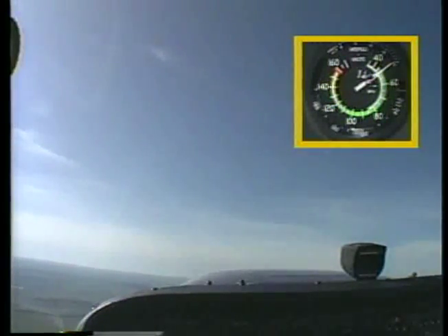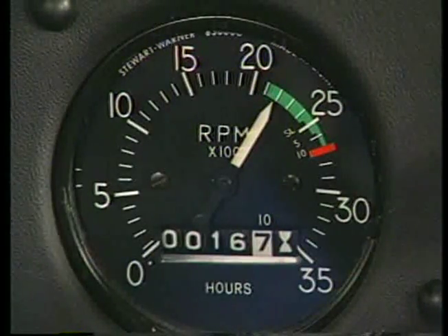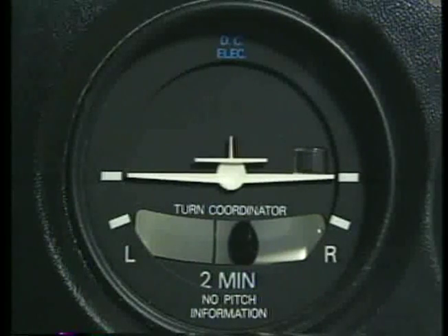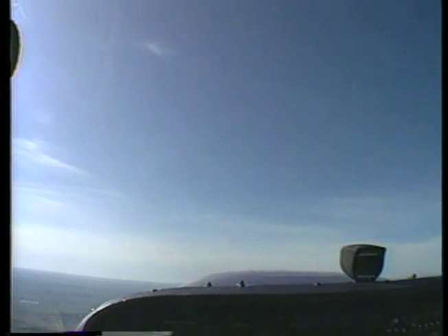When the airspeed approaches the desired value, increase power to hold the assigned airspeed and altitude. As power is added, smooth application of the right rudder is required to overcome the airplane's left-turning tendencies. Then, when attitude, airspeed, and altitude stabilize, trim the airplane to relieve control wheel pressures.